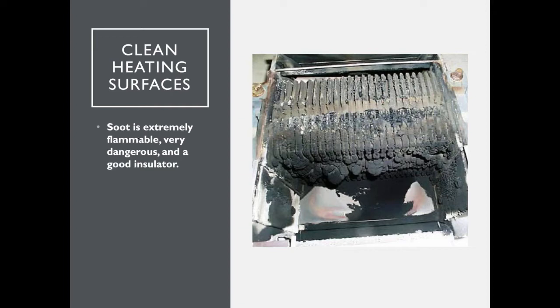Well, he hit the boiler one time with a wire brush. It ignited the soot. He got 3rd-degree burns up his arm and 2nd-degree burns on his face. He never came back to work because he was burned so bad. If I'm cleaning a sooted boiler, a lot of times I'll get a little spray bottle from a dollar store and just spray it with water. And then I use plastic brushes to clean it so that it has less likely of a chance to ignite.